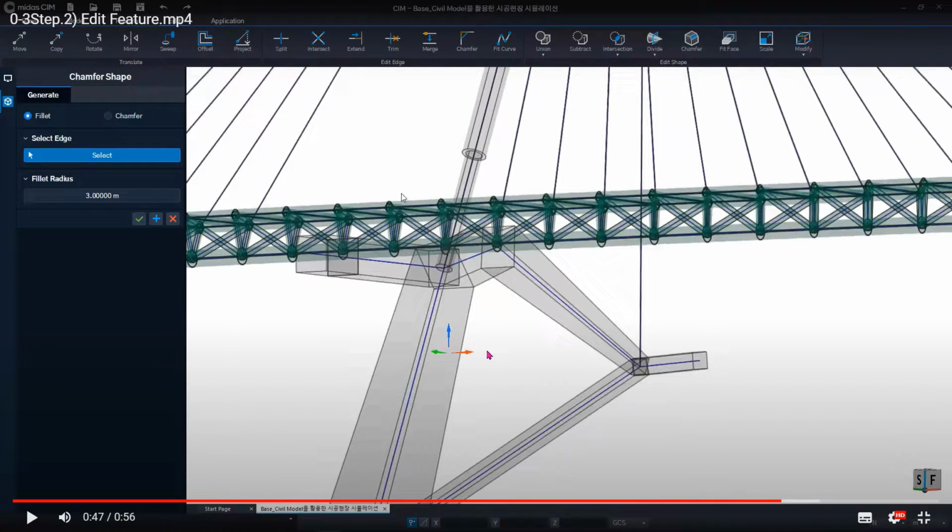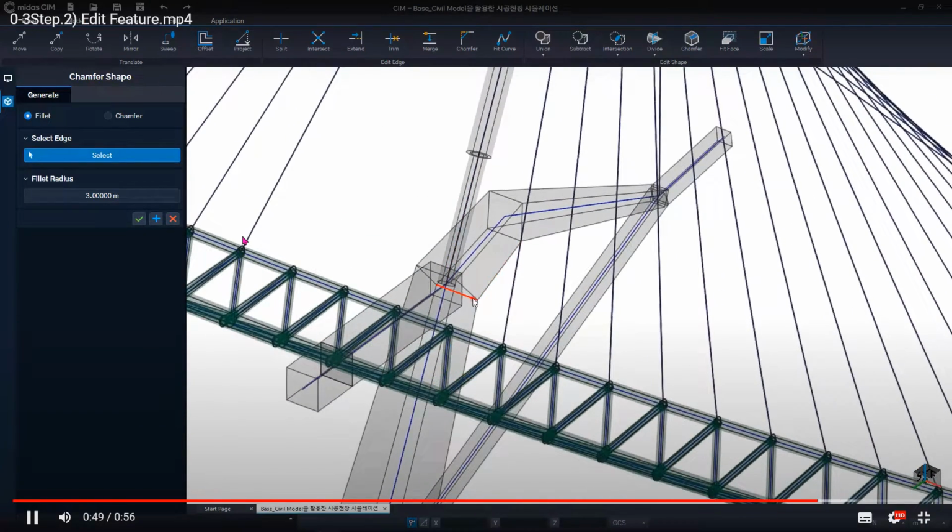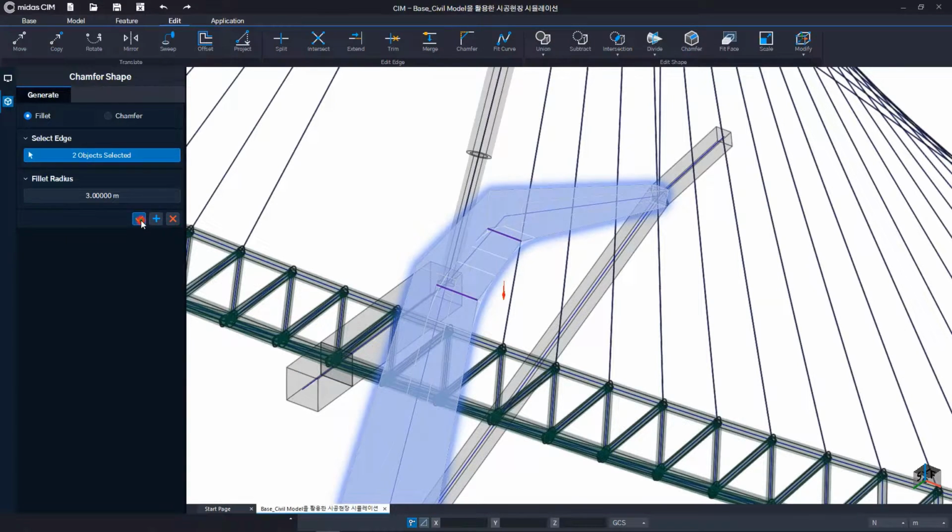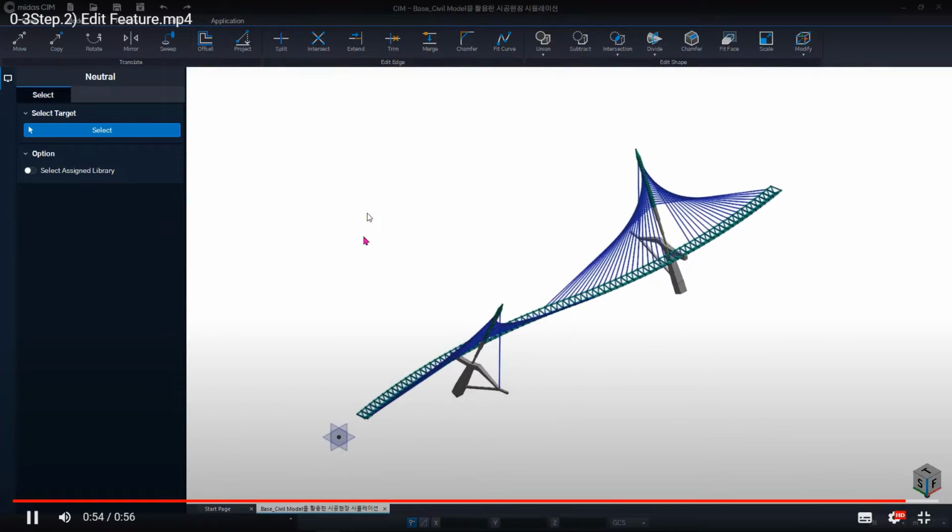So this is also important. If you want to add more things with a similar setting, you can click on the blue one, the assign part, so that you can click them, and then after you click on the blue part, you can click on the other with the same setting. You can click on the blue part as well. So it's like assign and finish. Yeah, you can click on here, and then you click finish. So it will automatically close the menu.